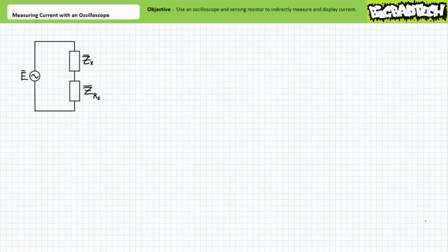Essential to this technique is your understanding of basic series circuit properties. Current through elements in series with one another is the same, and the summation of all voltage rises is equal to the summation of all voltage drops. We'll examine basic properties of series AC circuits in later lectures. However, they're essentially a repeat of basic series DC circuit properties.